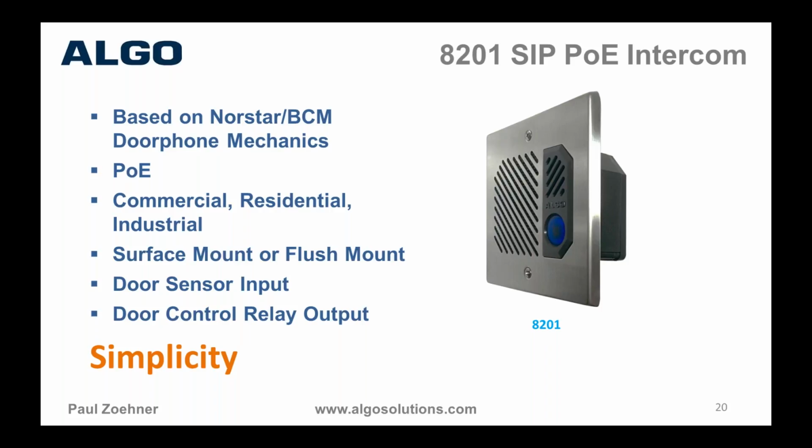It's an all-in-one, very compact. It can be installed in a double gang electrical box. It can be flush mounted or surface mounted. There's an RJ45 jack on the back. This requires Cat5, Cat6 cable to the intercom location.